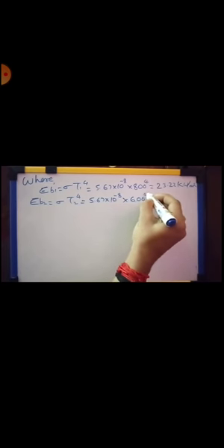Where EB1 is equal to sigma T1 raised to 4, which is 5.67 10 raised to minus 8 into 800 raised to 4, we get the value 23.22 kilowatt per meter square. Similarly, EB2 is equal to sigma T2 raised to 4, which is 5.67 10 raised to minus 8 into 600 raised to 4, is equal to 7.35 kilowatt per meter square.